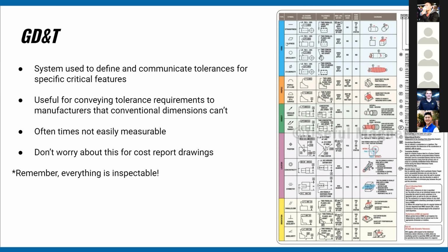And I found that sometimes people will read a position tolerance and just use that dimension as a normal tolerance. Basic tolerance is actually something else entirely. Like I said, try not to use these unless it does actually make sense for your part. Otherwise, it may just add confusion and more cost to inspect or qualify it.